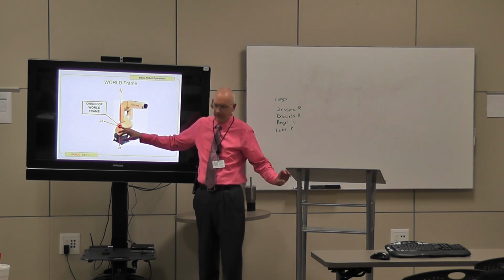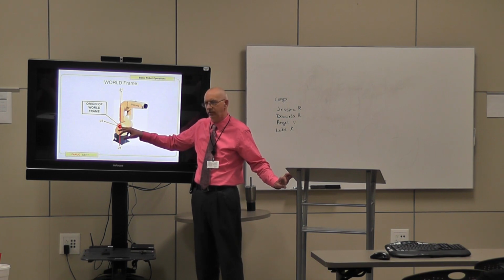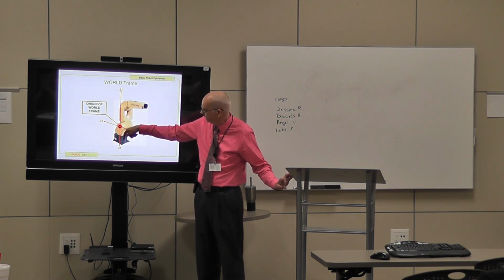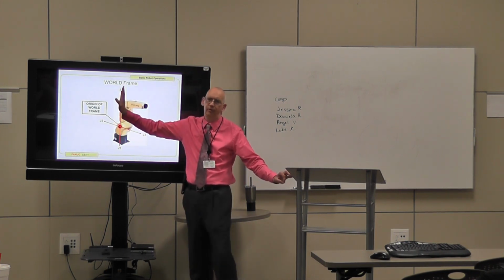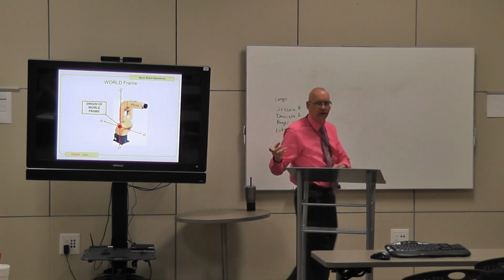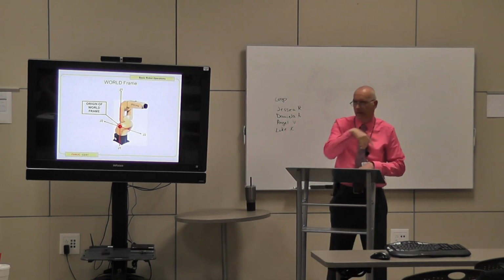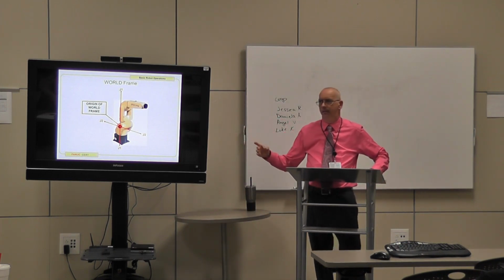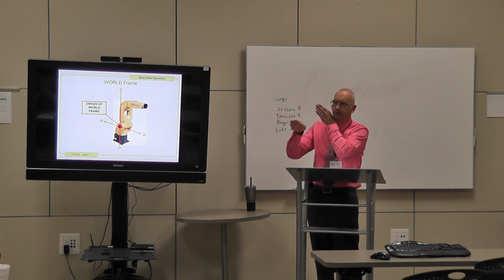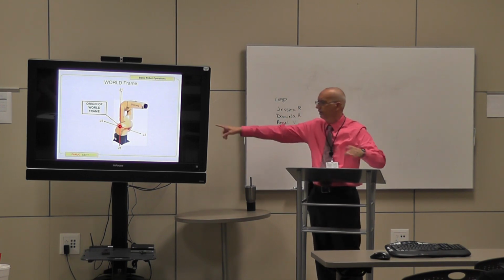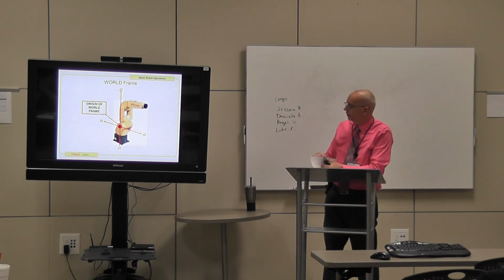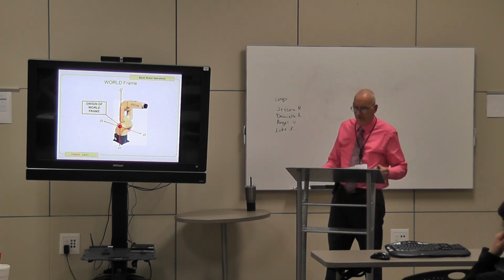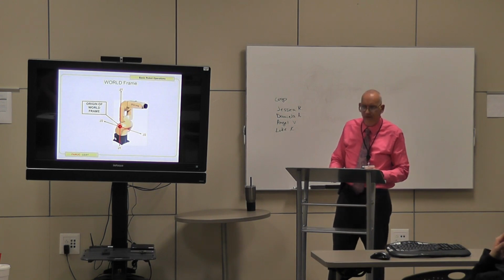This is joint 2, joint 1 being down here, but it's the center along this perpendicular of joint 2. Remember, in the lessons prior to this, I showed another type of robot up there with the servo motors going across. Here, obviously, you can see they're inside. So that is how you determine your origin for the world frame. Any questions on that so far?